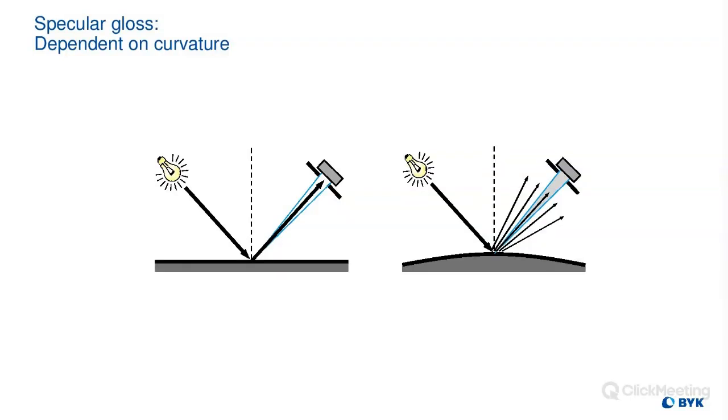For this, we either recommend creating some sort of jig, something that your piece, whatever you're measuring, can fit into, so that the meter is positioned the same way every time, or there is a continuous mode that I like to use when measuring curved surfaces like this. You can set it in continuous mode to automatically take a reading every second, and just slowly roll it across the surface, so that at least one of those continuous readings will be a good one. Then when you stop it, you can look up the maximum for the best value.